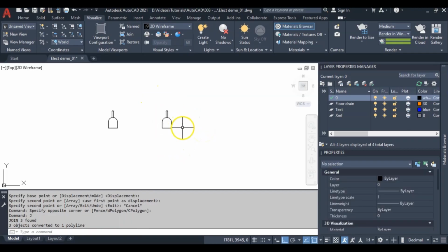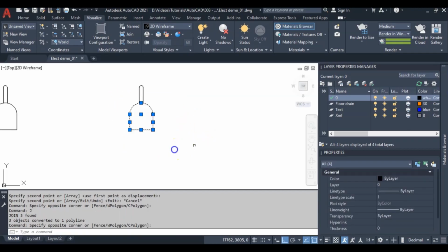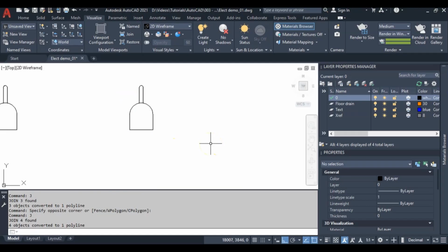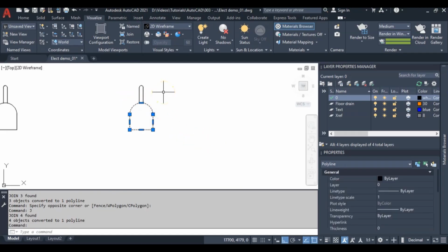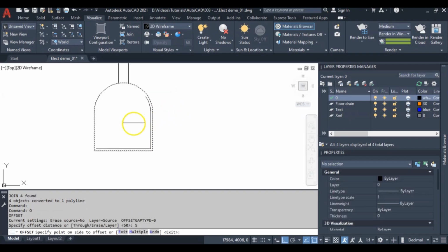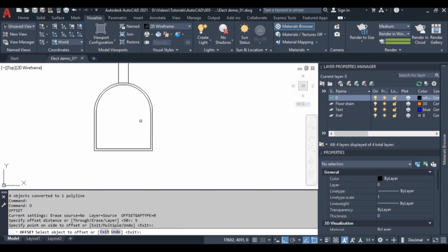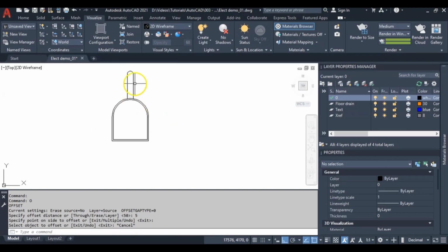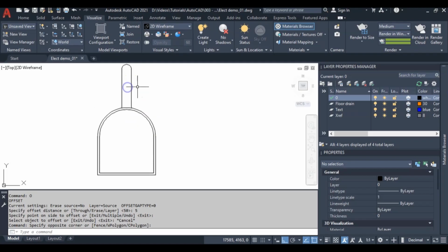This is just to create something a little bit more aesthetic. Then I hit join, just to join all the lines. Once done, you can highlight the line, then offset by maybe 5 mm just to get a little thickness inwards. This I leave at your discretion. You can go 10 mm if you like.